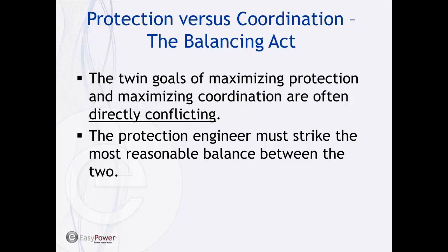It's important, prior to performing any coordination study or trying to reduce your arc flash hazards, to completely understand the system that you're looking at, so that when you adjust settings to improve the protection, where worker safety is the number one factor, you're not overlooking other hazards that may exist.